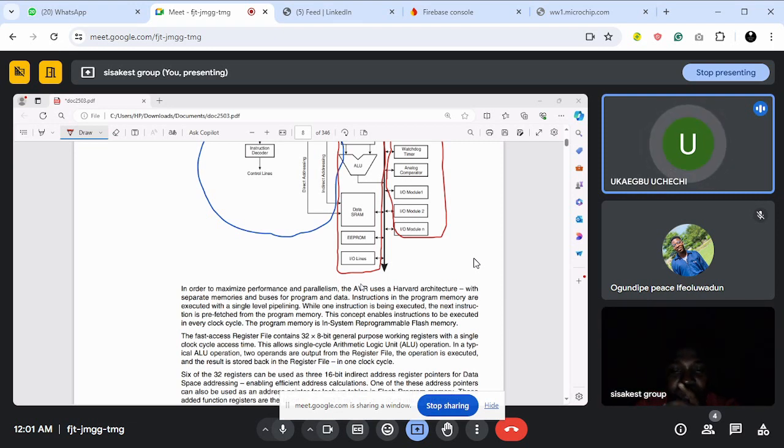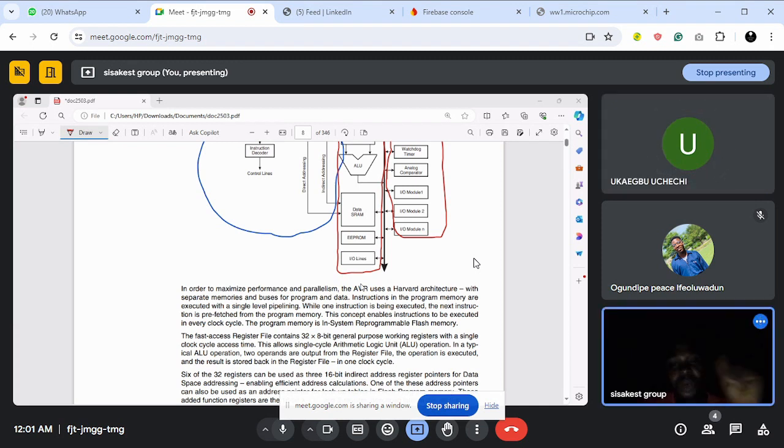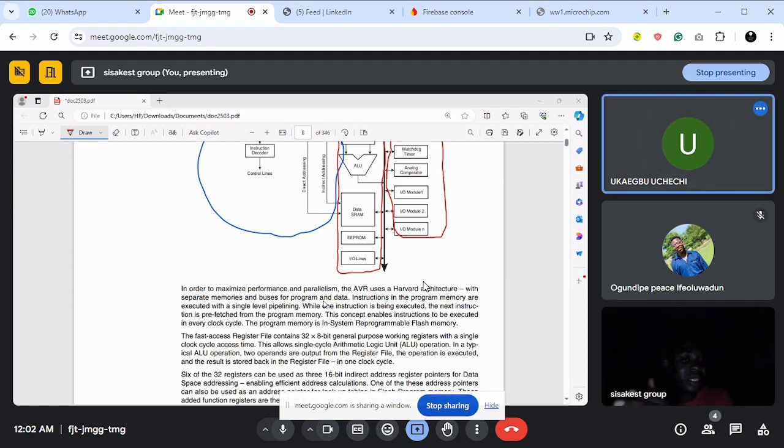So I want to ask, the data memory you mentioned, is it the same thing as the working registers, like the one you circled in red at the middle? Yes, it's the same thing as the working registers. So it is the major registers that the processor might manipulate. So you understand now. Now the literal pins here, the pins of the microcontroller, are connected to these working registers.